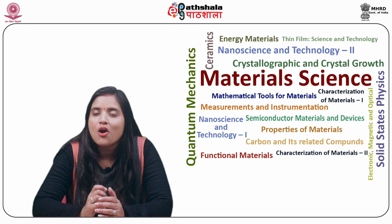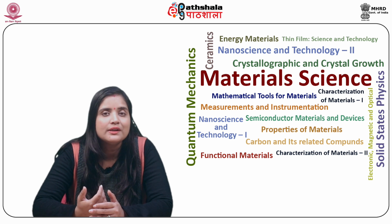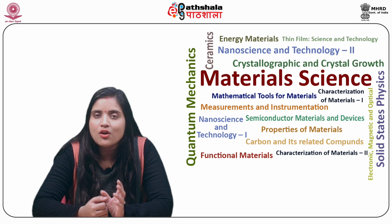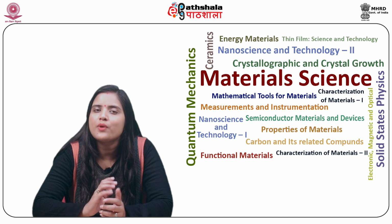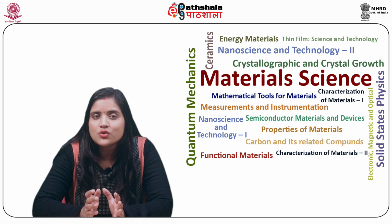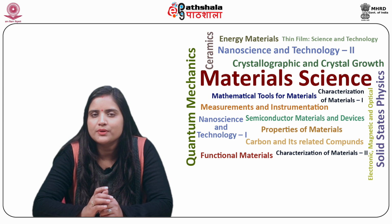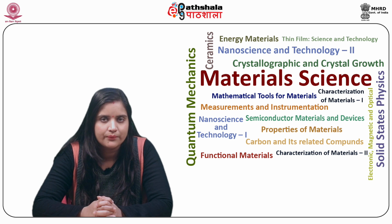Electroless nickel Teflon composite now. This is the recent application area of the electroless nickel plating technique. Teflon coating yields a very low interfacial friction. In this technique, microscopic beads of Teflon are co-deposited up to 20% along with the electroless nickel.